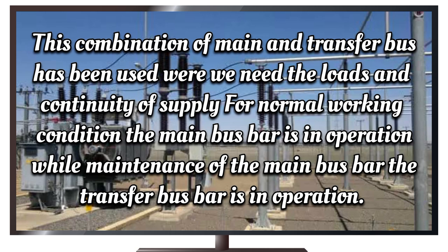This combination of main and transfer bus has been used where we need the loads and continuity of supply for normal working condition. The main bus bar is in operation, while during maintenance of the main bus bar, the transfer bus bar is in operation.